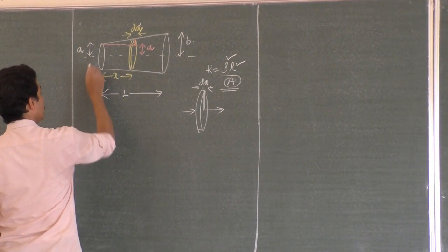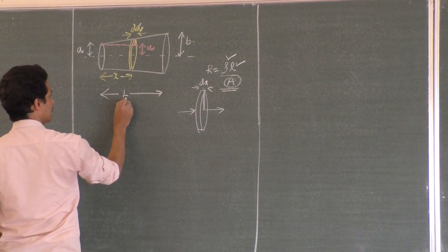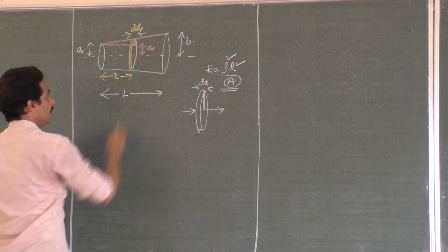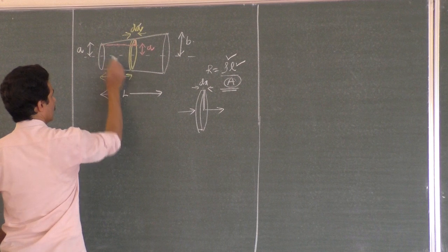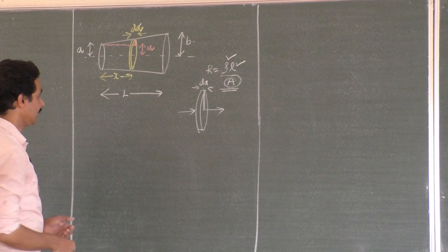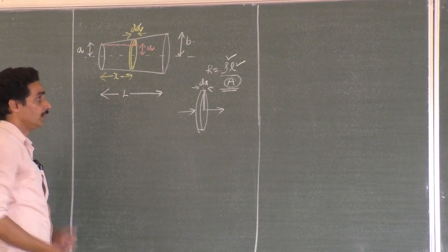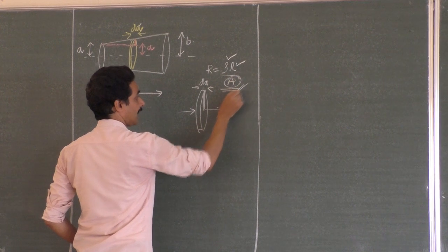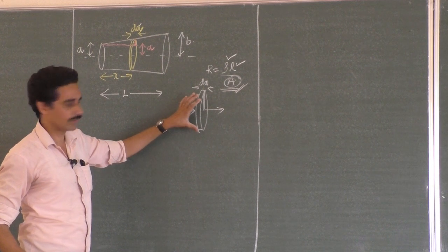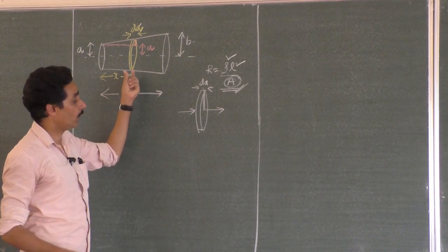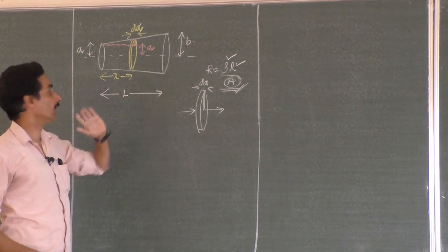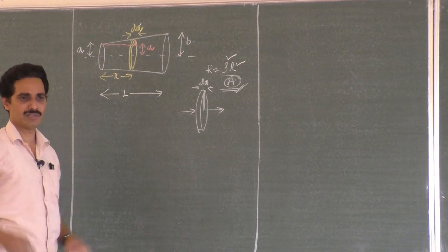Since it is a linear variation, when you move from this end to that end, that is when you move through a distance of L, you get a change in the radius as b minus a. Am I right? So when you move through a distance x, what is the change in the radius from a to what value? That is what you have to do. Did you get that? Because we are trapped here now. If you get the area value, then you can write the resistance of the small piece of the material. Once you get the resistance of the small piece, you can integrate it from left, a, to right, b, from here to here, and then you can continue it.